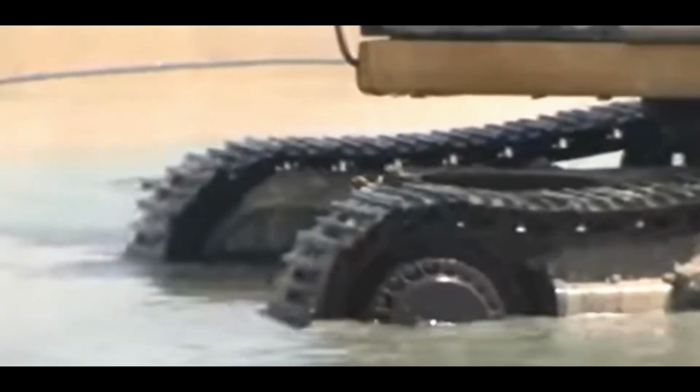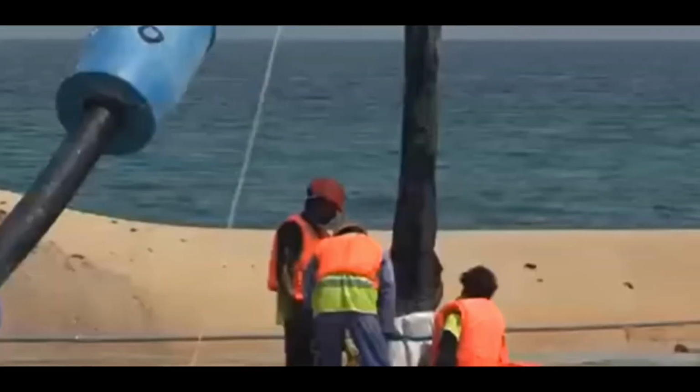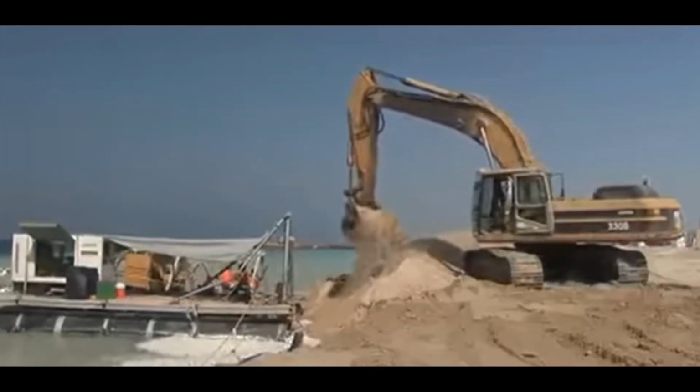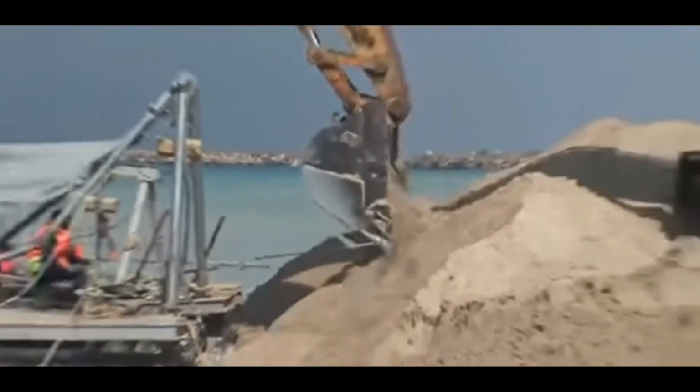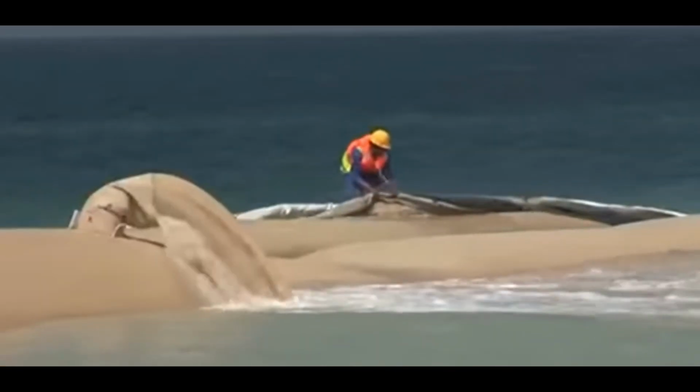An abrasion-resistant submersible pump with agitators and a hydraulic drive of 75 horsepower was hung in the middle of the air above the slurry pit. Then another 6-inch and 8-inch self-priming trash pump was used to supply the seawater to the pit. Both pumps supply water at a rate of about 1,700 gallons per minute.